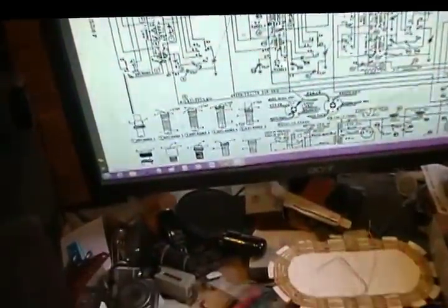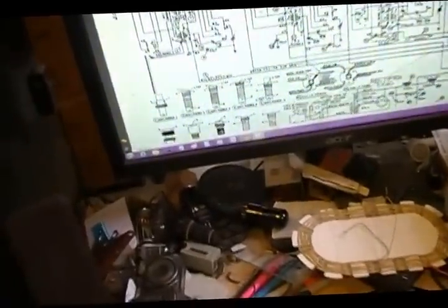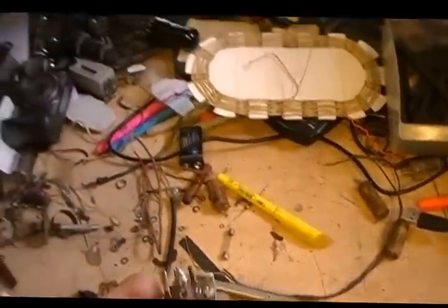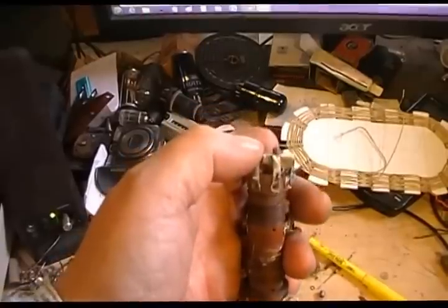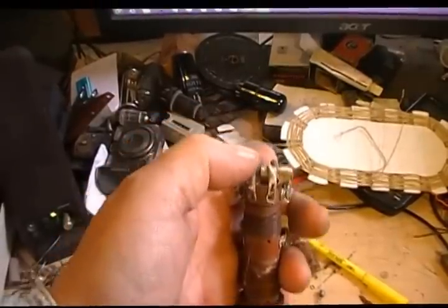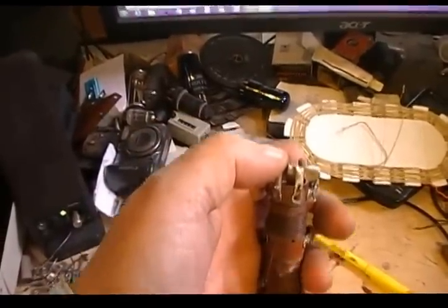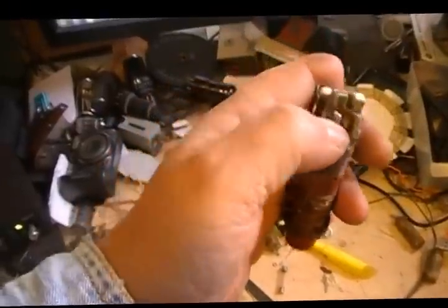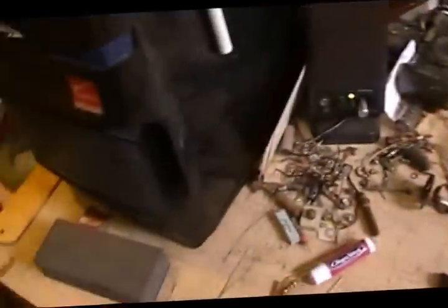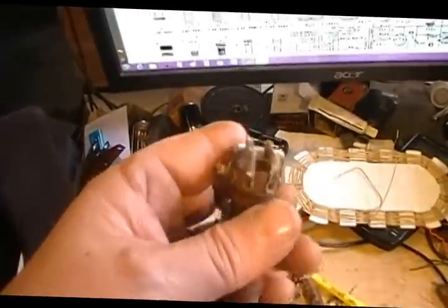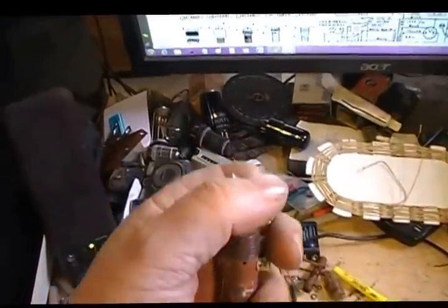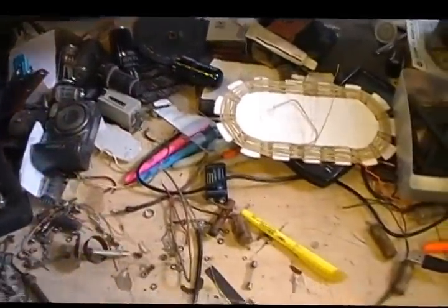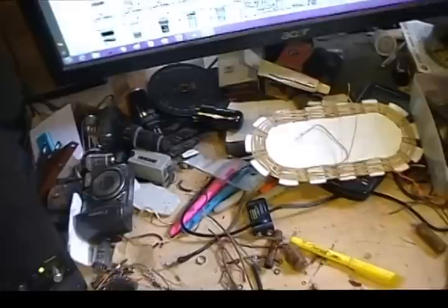Even if you're never going to pull the coil out, you don't know for sure, take pictures of it and document. It may have colored wires on it. Maybe this one had red and this one had blue. Well, then document that. Take pictures and then also write down and show the coil drawn out like I showed on the drawing here. And then you can say red wire goes here, call it pin 1, blue wire went to pin 2, and so on.